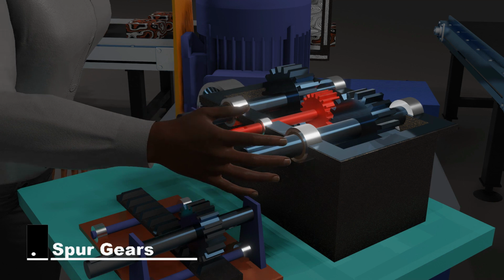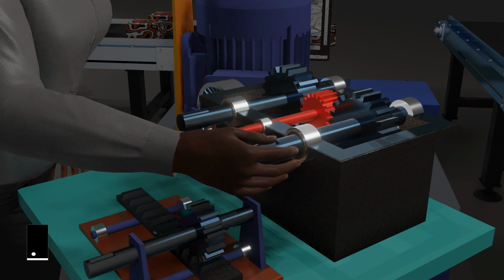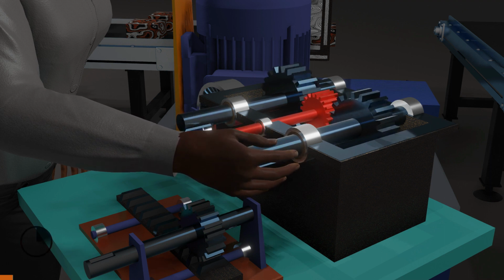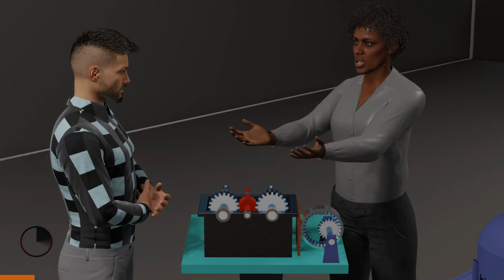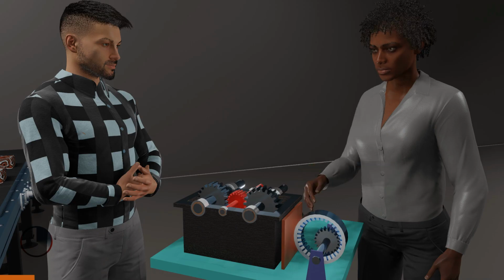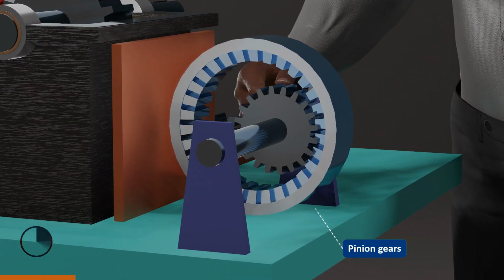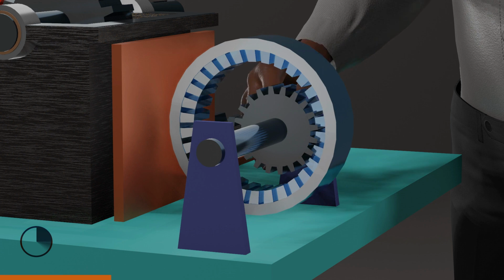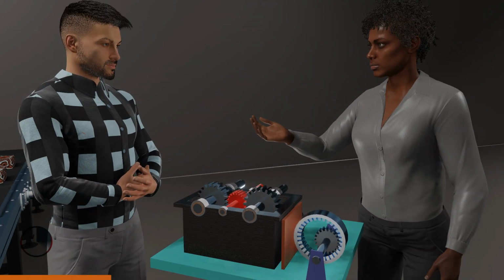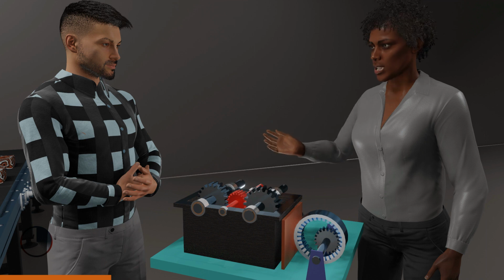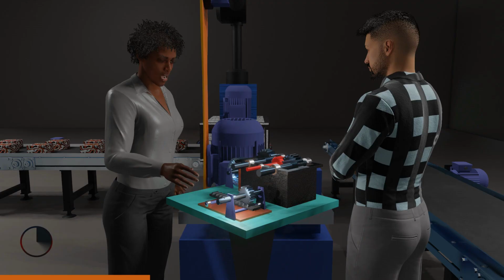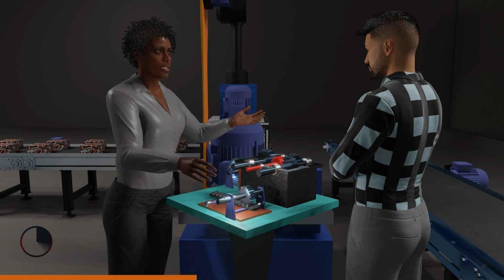External gears are gears with teeth cut outside the cylinder. In a mechanical setting and during motion transmission, two external gears mesh and rotate in opposite directions, while internal gears are gears with teeth cut on the inside of the cylinder. So in a mechanical setup, an external gear, which will now be called a pinion gear, sits in the internal gear, and the gears rotate in the same direction. Because the shafts are closer together, internal gear assemblies are more compact than external gear assemblies. Also, internal gears are mainly used in internal gear pumps and planetary gear sets.